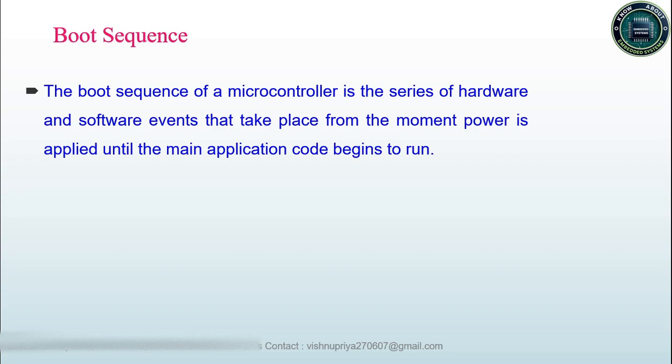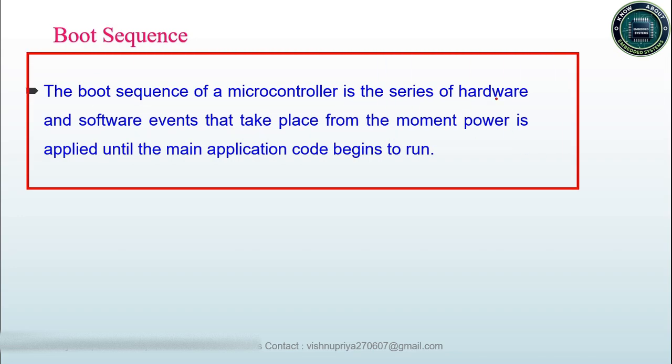The processes occurring, software or hardware events, from the reset till you reach the main function is called the booting sequence. So the booting sequence in a microcontroller is a series of hardware and software events that takes place from the moment power is applied until you reach the main application program. That means from when you apply the power till you reach the main program, this entire process is called the booting process or booting sequence. Okay, so I hope you are clear.